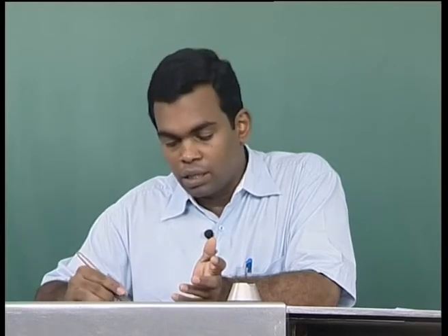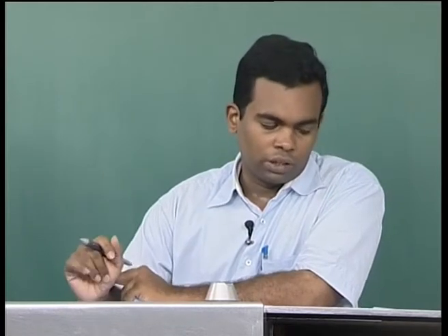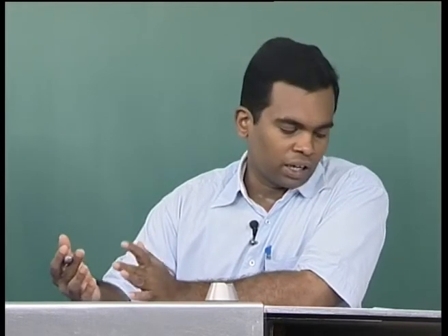Because if you keep on increasing the velocity or flow rate of this gas, then at some point it is possible that the solid particles will flow outside the column, which is not required. So, a clear knowledge of the flow rates of the gas at which the bed will remain fluidized, but again does not result in unwanted effects, is very, very critical. And again, all these aspects are essentially fluid mechanical in nature.